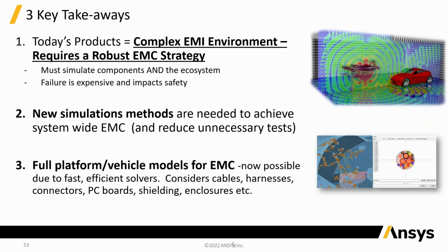Yeah, so the biggest thing is a dedicated graphics card, one of the newer ones. That's really important for setting up the model because Discovery requires it. You can run these on a laptop. A lot of people at our office do. I have a couple-thousand-dollar desktop that I can run it on. The 12 hours for the airplane, I think was running on 72 cores, so 72 processors. So that was actually quite a big computer.